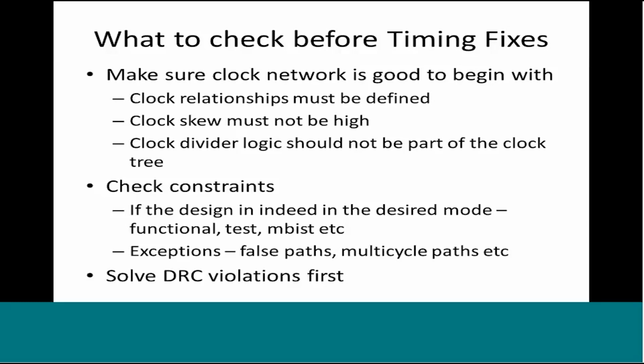What the scripts or any automated ECO engine would do is take all the reports as input, for all the modes and for all the corners. It needs to know what the violation looks like in different corners, and whether the path has enough margin to fix setup or hold.